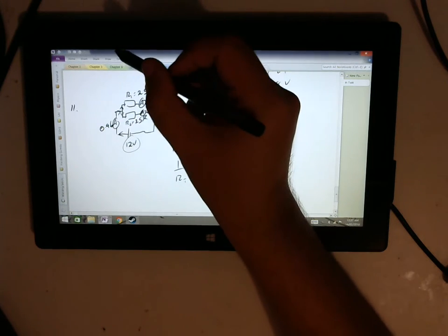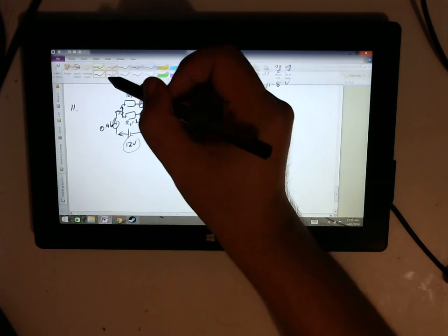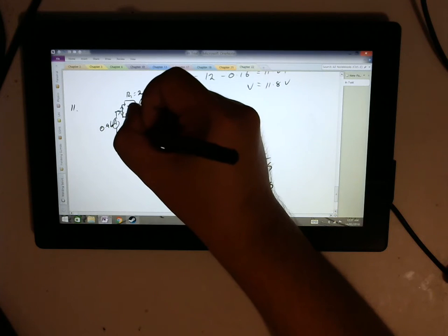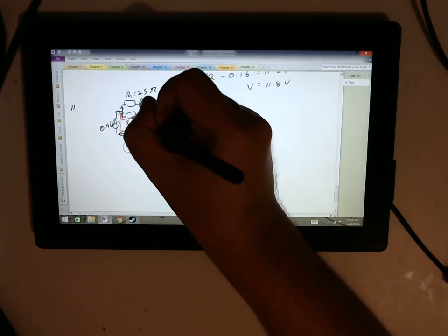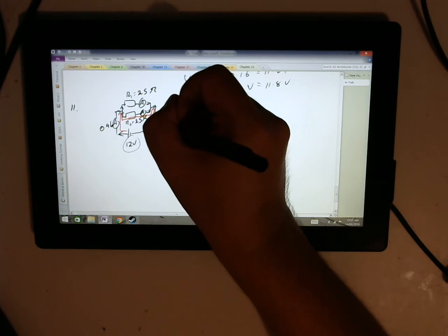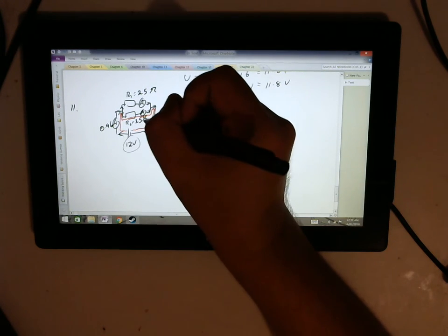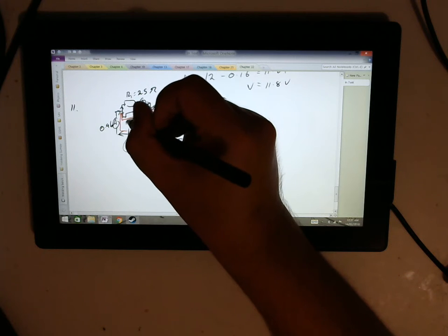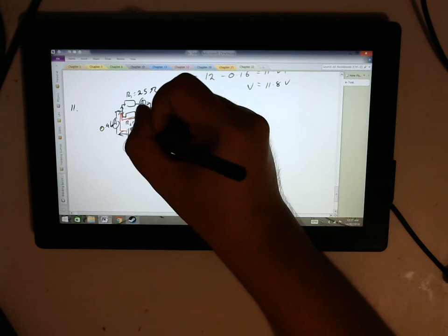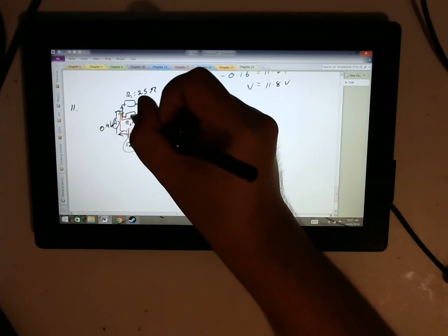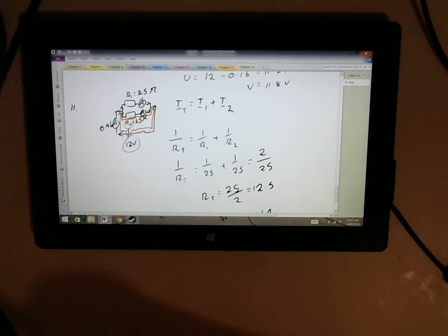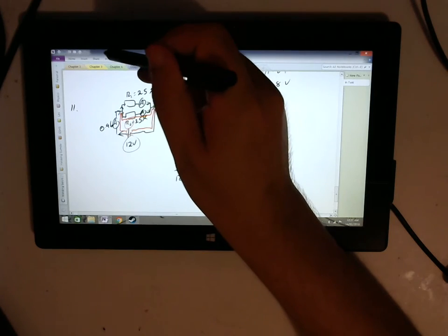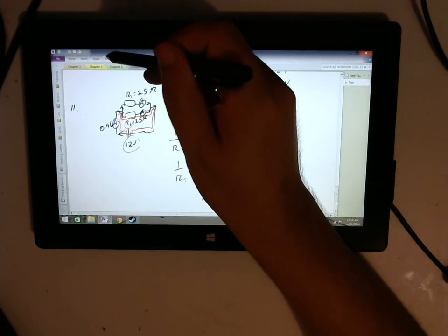I'll do this in red. So let's draw one path. We leave here, we go here, we can choose to go one way. Let's go down, we go through here, back up, and then down and back to here. So we can see if we go around this path, it gains some voltage here, and it only goes through one resistor, so it has to lose all its voltage there. That's a sort of hard thing to wrap our head around, that it must lose all its voltage there.